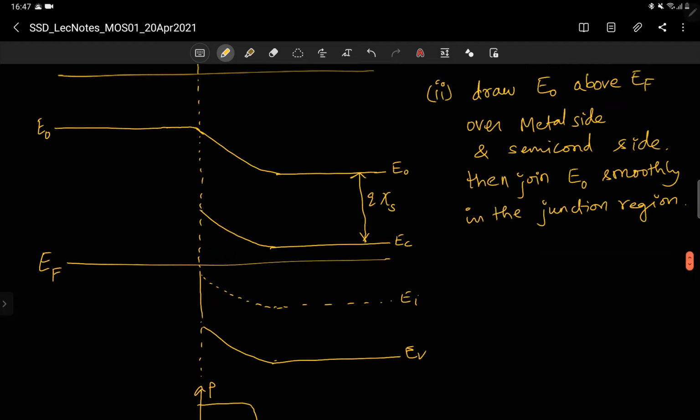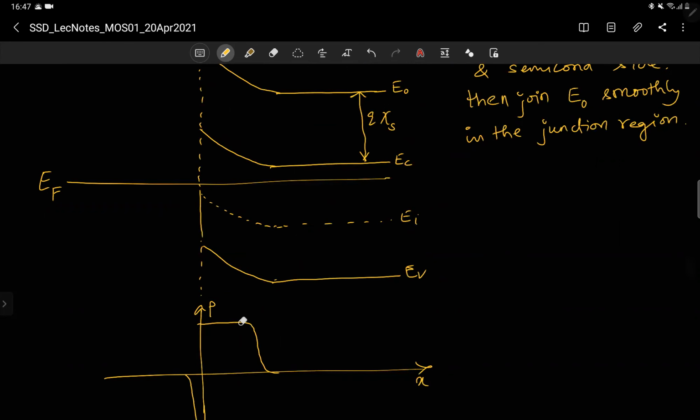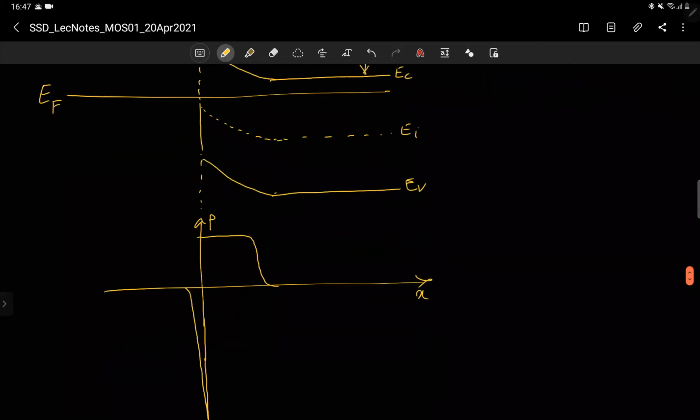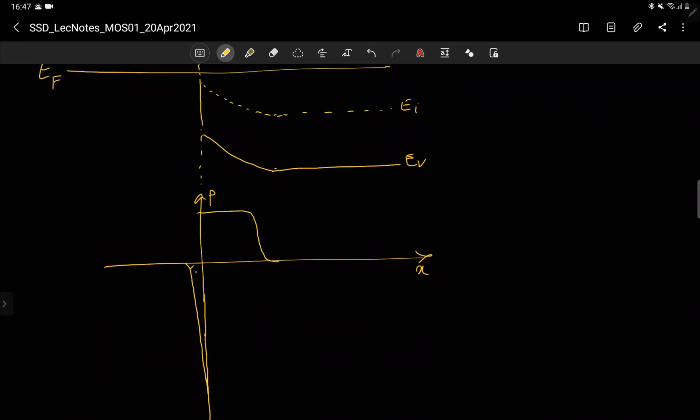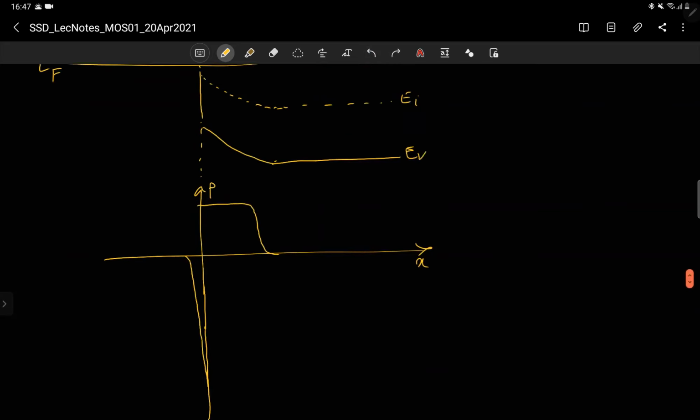Here the concentration comes from ionized dopants, which have a fixed concentration of Nd. But electrons can just come into the metal region and vary rapidly. Both areas under the two curves, on the right hand side and left hand side, will be the same. So this is how the space charge density looks.